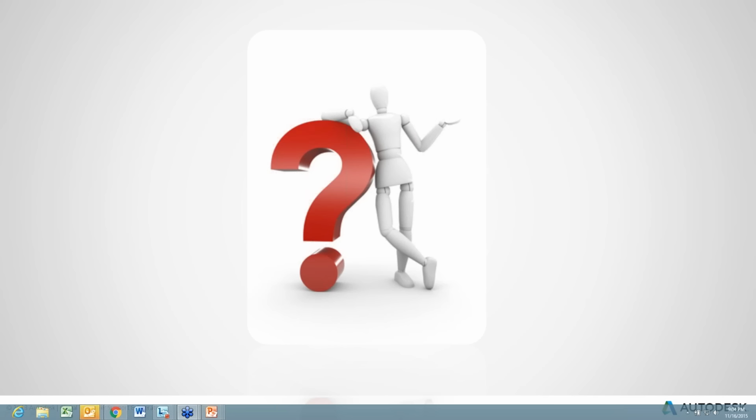I suggest going to Autodesk.com and doing a search for network to standalone, or standalone to network, whichever way you want to do it. Either way, you're going to come up with an article that will show you which registry key to go in and change. It doesn't work 100% of the time, and it's only AutoCAD-based stuff. Sometimes Inventor can also, but usually just an AutoCAD-based product it will work for. Anything else, like a suite that includes a bunch of non-AutoCAD software, you will likely need to do an uninstall and reinstall to get that switched over to network.